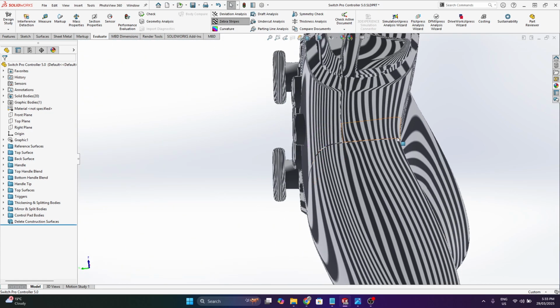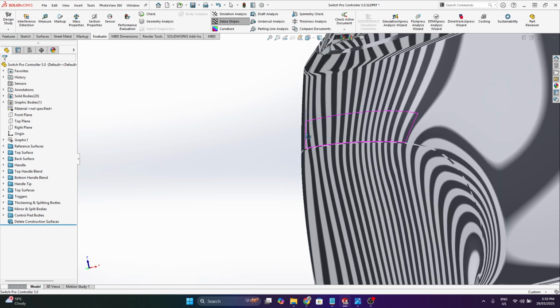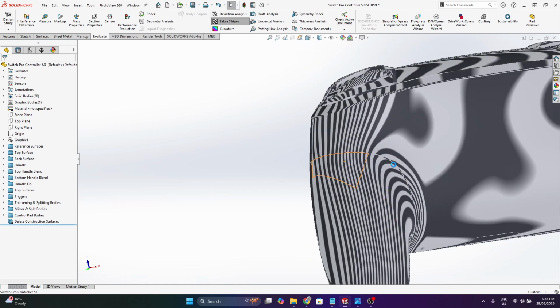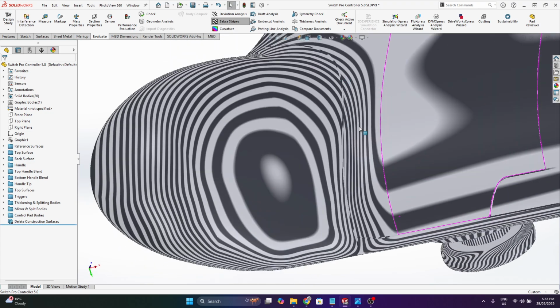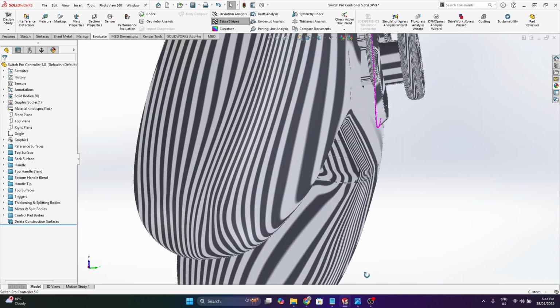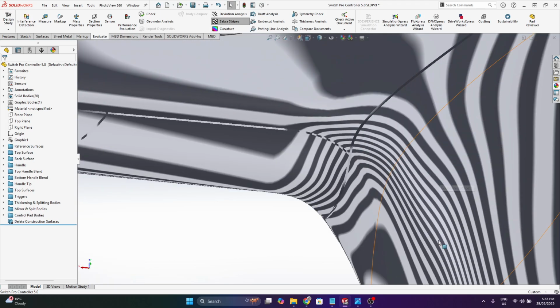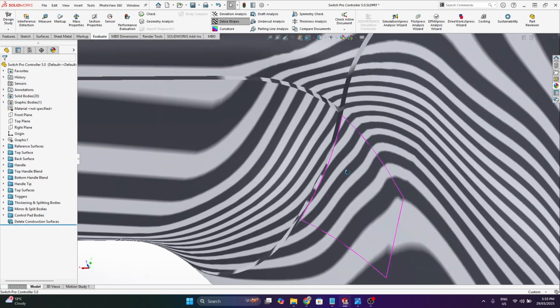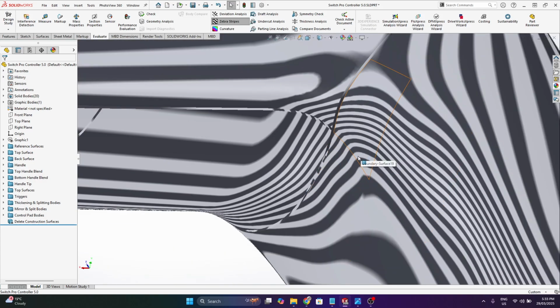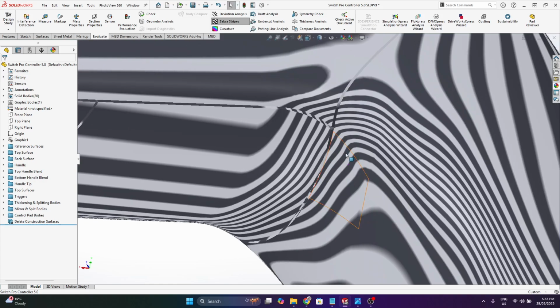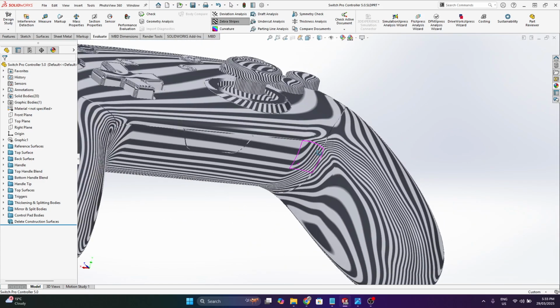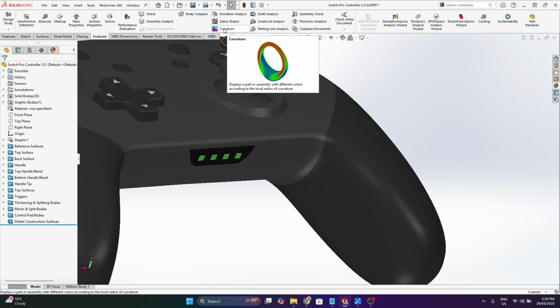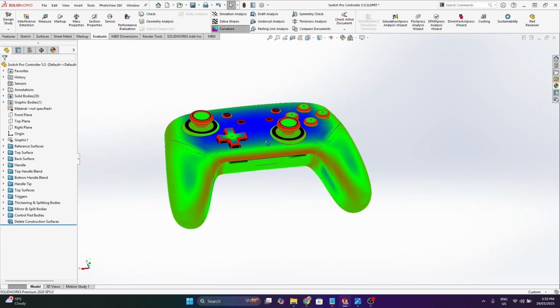This model isn't perfect, and I will go through that as I'm going through this video, but areas where there's a bit of wobbling, let me just find a good area. Yeah, so here you can see there's a bit of wobble as the zebra stripes go around these connection areas. That indicates that the surface isn't the best it can be, but this is okay. I was happy with this, and I'll actually go through some models I started with that weren't as good to give you a better understanding.